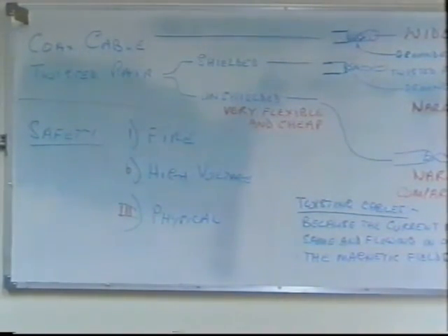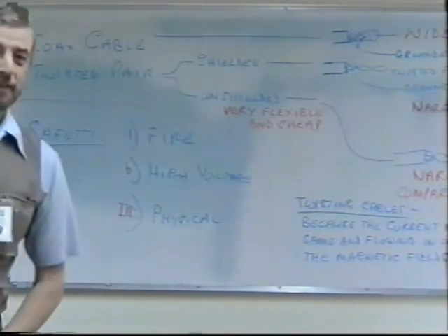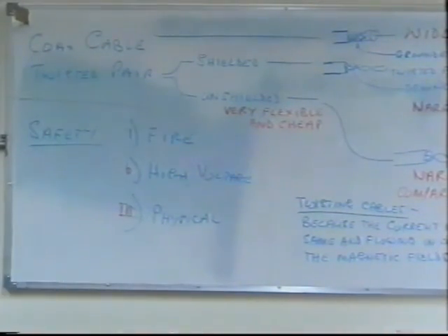If you're on top of an antenna and somebody suddenly decides to start transmitting while you're up there, you could again get an electric shock. The procedure should be that if anybody's going up the antenna, the power is removed. And again, there should be another person responsible down below to make sure the power is removed.